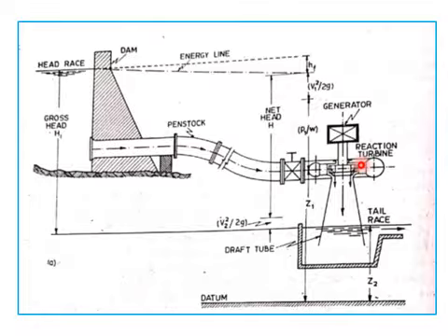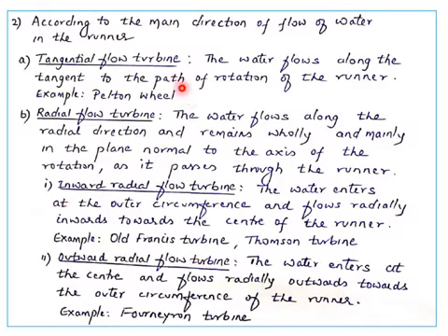However, the pressure at the outlet is getting converted, and the pressure at the inlet will be quite different from the pressure at the outlet. This difference of pressure created between inlet and outlet is known as the reaction pressure. That's why it is known as a reaction turbine. You need to guide the water to the tail race, so we need what is known as a draft tube here. It requires an airtight casing so that the conversion of energy takes place. The Francis turbine and the Kaplan are the examples for this.